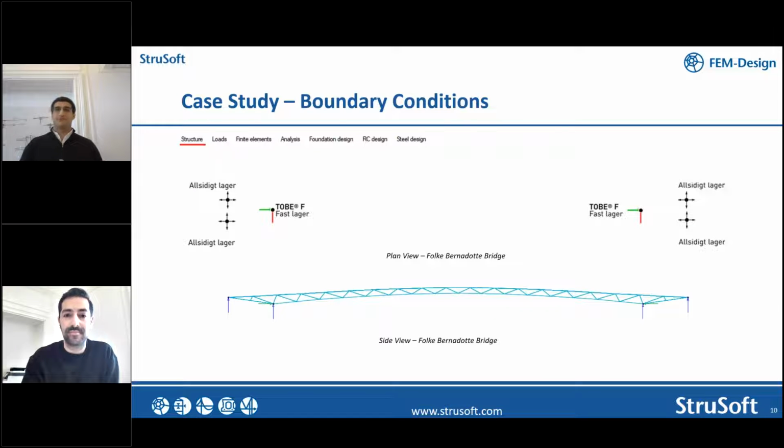For a footbridge, around 100 meters span is going to pretty much give you some problems in the frequencies, especially from the design perspective. And then when I saw that it is a 3D truss-like structure in stainless steel, I realized that yeah, this particular project may be a potential case study.